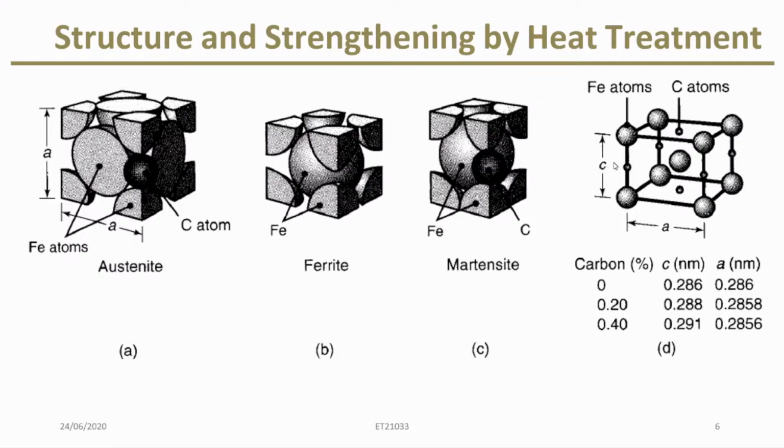Low tempering temperature sets the balance and maintains maximum hardness, and high tempering increases impact resistance and fatigue life. So heat treatment strengthens steel by engineering its microstructure.